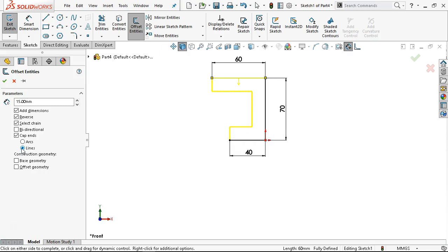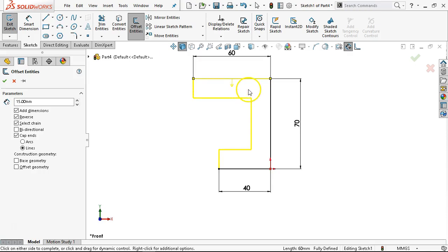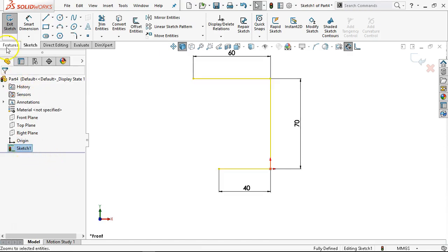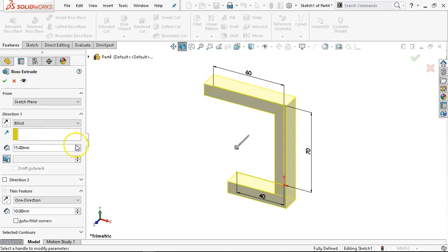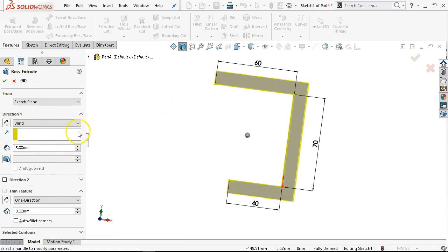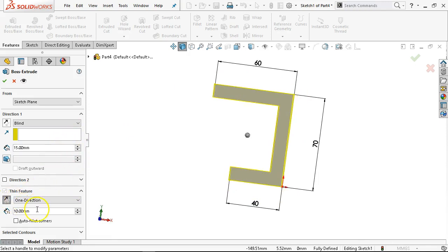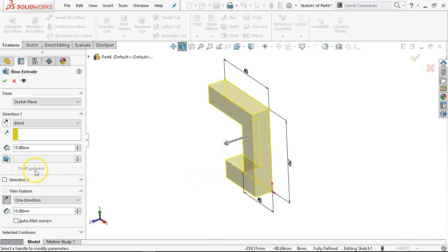All right, if there was something else that I wanted to include in this sketch, maybe there's a hole or notch geometry or something, this would be the better option if I was including a nested feature or another piece of geometry in this sketch. Okay, so since I'm going to stay with the thin feature and contrast it, we'll go back in, reverse the direction. It's going to be 15 millimeters, and the depth of 50.